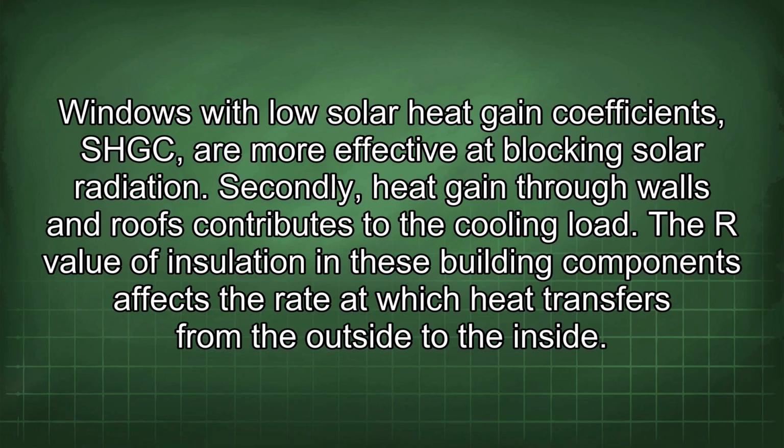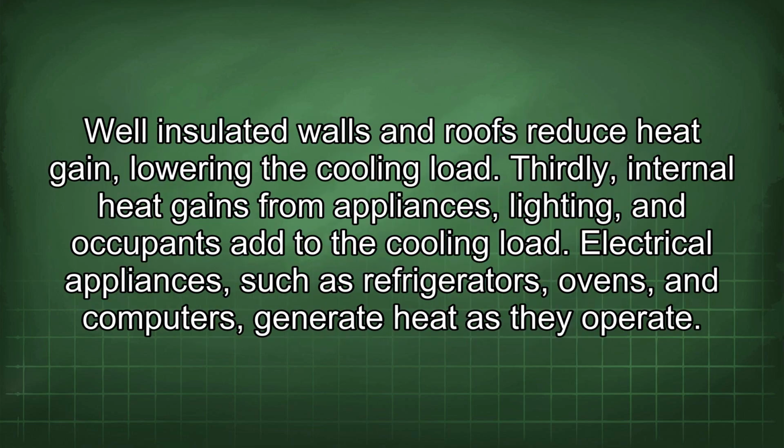Secondly, heat gain through walls and roofs contributes to the cooling load. The R value of insulation in these built-in components affects the rate at which heat transfers from the outside to the inside. Well-insulated walls and roofs reduce heat gain, lowering the cooling load.